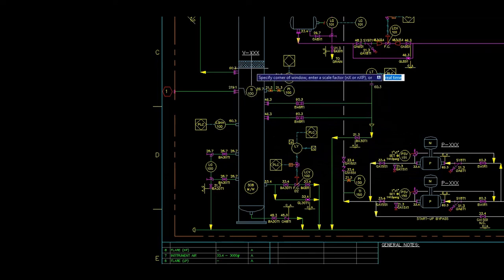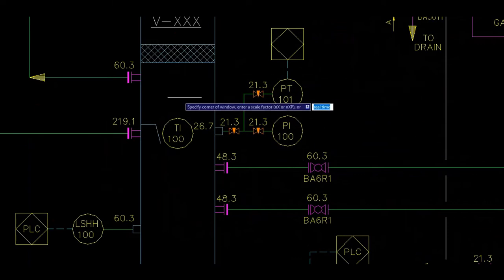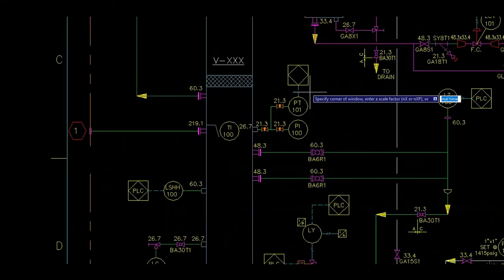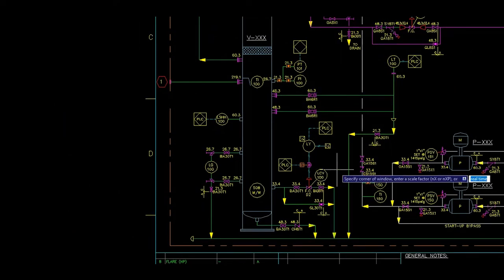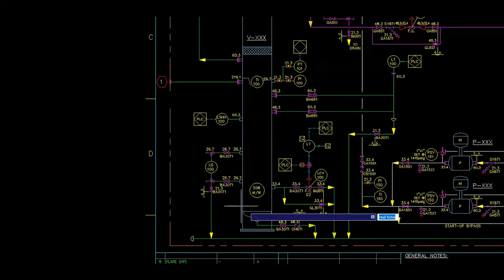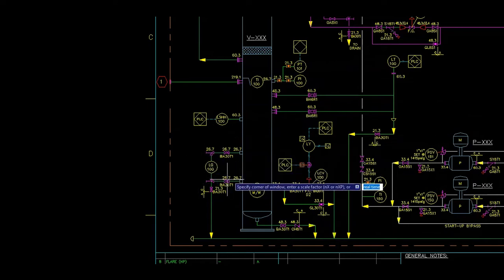As soon as the gas enters the contactor, temperature and pressure will be displayed in the control room. This piece is relaying pressure to the control room. The following instruments are for this section of the contactor: a level transmitter, a local level gauge, and a snap-acting dump valve which removes all the breakout water described earlier.